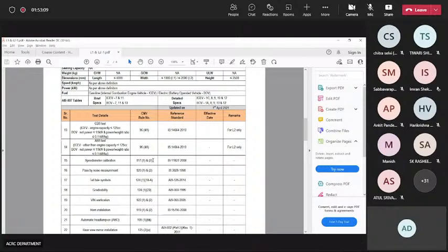And again, there is a requirement of ABS in the vehicle when your vehicle is an IC engine and the capacity is more than 125 cc, then you need to have ABS. The CBS will not suffice. And if it's a battery operated vehicle, an electric vehicle, with net power more than 11 kilowatt, then you need to have ABS. Otherwise, if it is below 11 kilowatt, then you can have CBS itself. And if it is in the L1 category, even the CBS is not mandatory. So those things are well defined, and the standard is already defined, IS 1464.